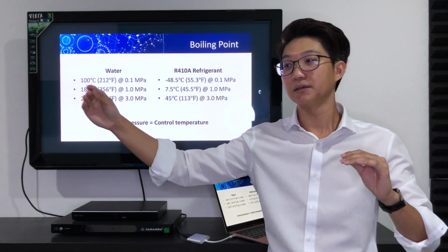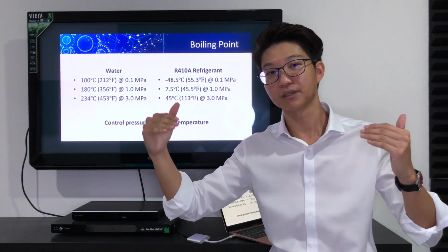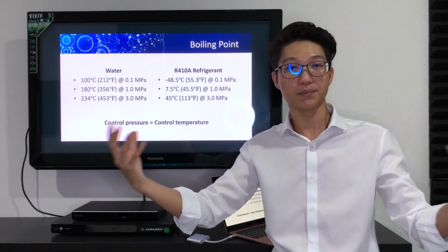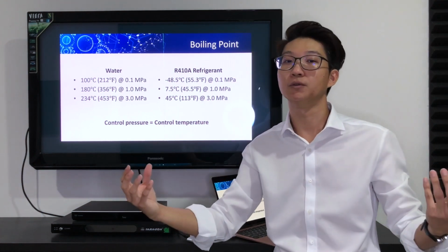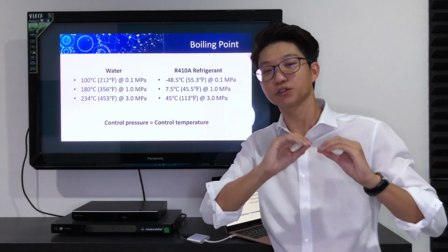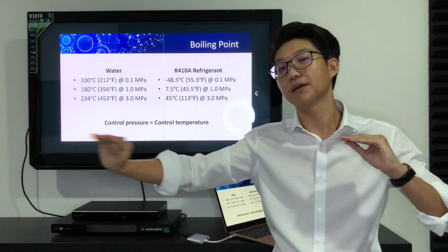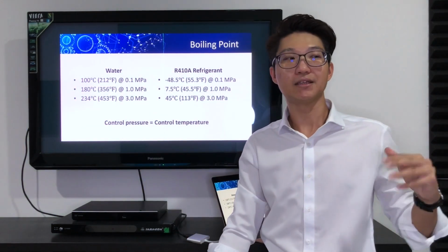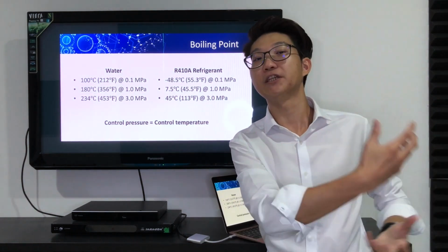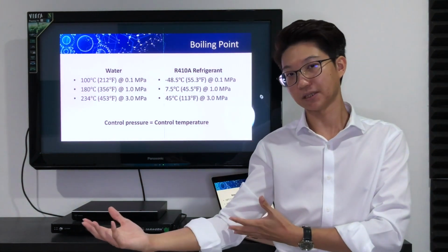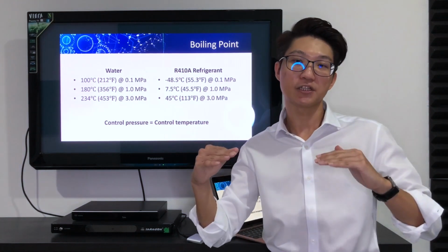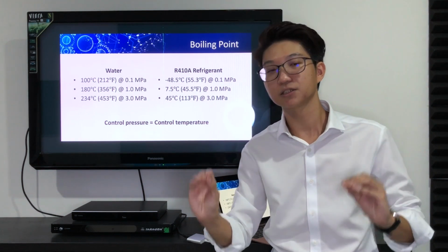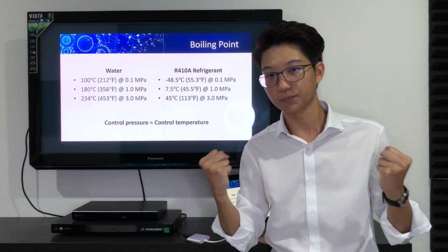Eventually, it no longer has what we call the temperature difference, or delta T, to absorb heat. That means it is no longer useful. We want to extend the usefulness of this substance as long as possible. So we know that during phase change, energy is used for the phase change process instead of increasing the temperature. That's why during phase change, the temperature remains constant. That is what we want. We want the temperature to remain constant so that it continues to absorb heat.